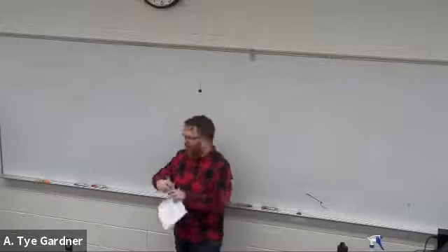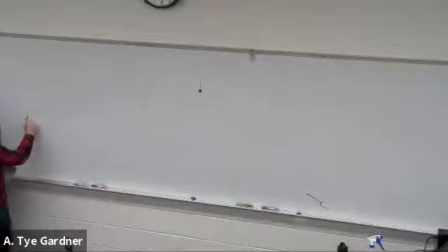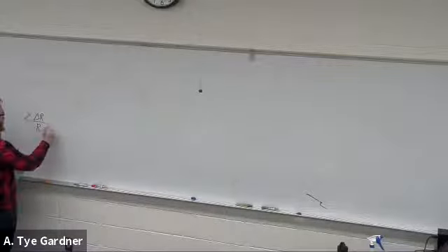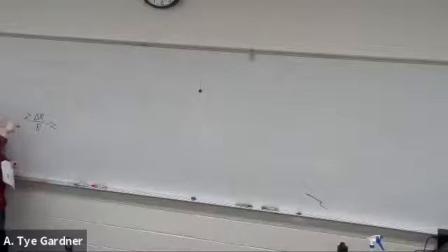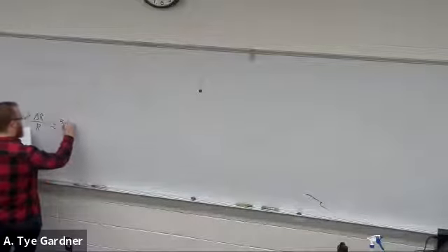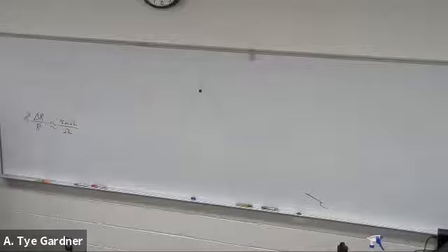And unfortunately, and this is why things are awful, your delta R by R in this kind of wire measurement system ends up being something terrible like 5 milliohms per ohm. It's very small. You don't get much change in resistance, which means at the output, your change in voltage is also very small.